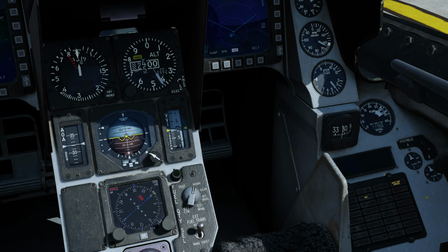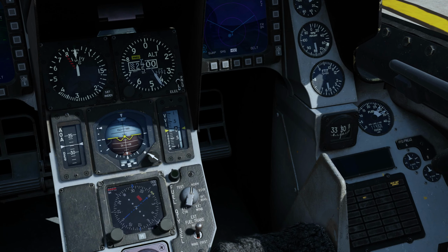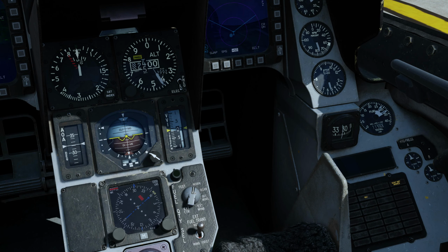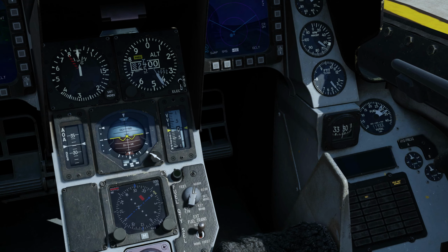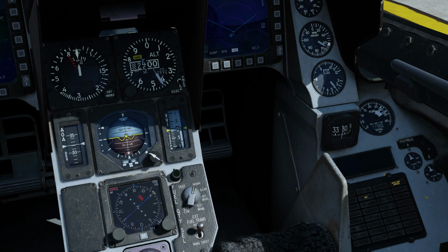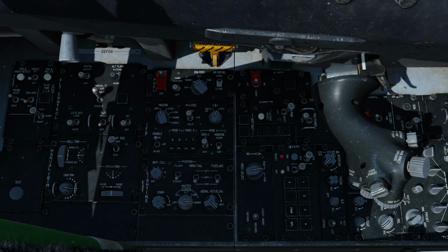Verify smooth RPM operation in secondary mode. Note that RPM may be lower. Return engine control to the primary position.